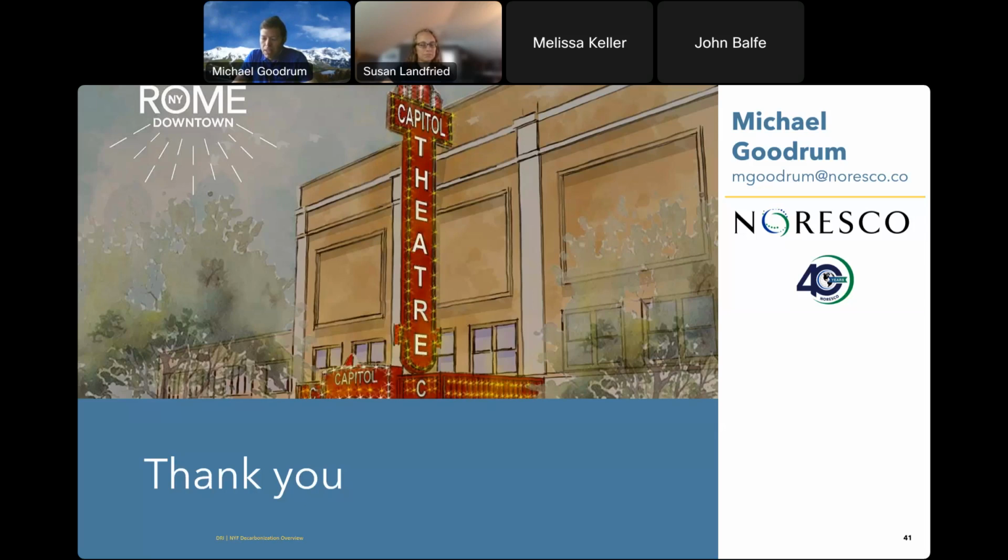One of the interesting things we talked about, I had the slide about thermal storage, and that was really thinking about water tanks or maybe chilled ice. But I have seen for older buildings that are heavy masonry construction or stone, where you could look at actually using the mass of the building itself as a form of thermal storage.